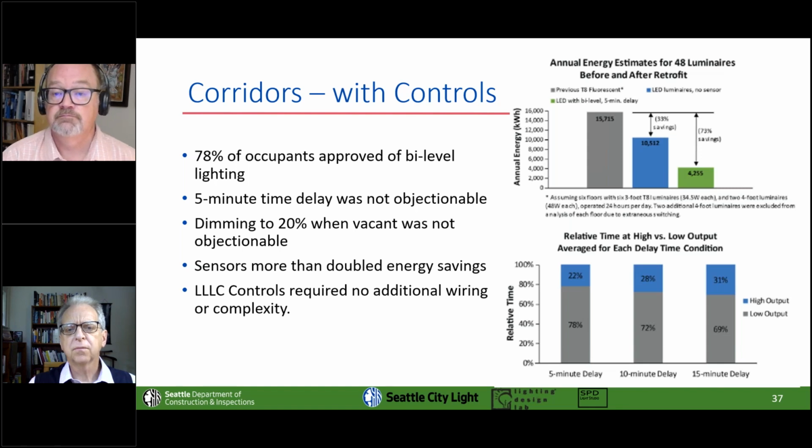So Shaun, when you look out the peephole in your apartment door with 20% light out there, you're still fully able to see who's in the corridor? Yeah, you may not see quite the same detail that you would see once the lights ramp up again, but you absolutely are not walking into darkness. And the sensors react very quickly. Again, we're talking about a sensor per light fixture. So there are a lot of sensors in the corridor there. And as soon as they see you, they're going to ramp the lights right up.